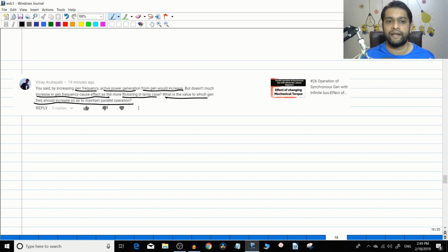Remember that. So anyway, go through these videos once again, then I think you will have a clearer idea. In them I explain parallel operation with an infinite bus bar and parallel operation of two generators also. So you see that video and you will understand the phasor diagrams, etc. You have to watch those videos properly, and you will understand the concept. So remember, active power adjustment is torque input or mechanical input adjustment, and reactive power adjustment is field current adjustment.